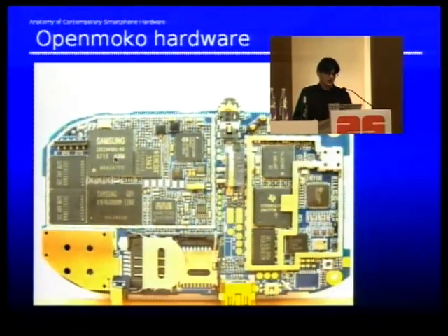We have the system on a chip here. This is the one which does not have the integrated flash and SDRAM. So we have the flash here, SDRAM here, and the S-media here is the graphics accelerator. This one, the PCF50633, is the power management unit, which is the same that is used in the iPhone, by the way. We made NXP open the datasheet, so I'm sure people can have creative uses for that. That's the Wolfson codec for the audio side, and that one, I think, is the audio amplifier over there.